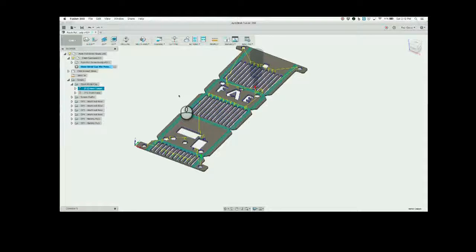And if Edwin needed these changes to the board, all he would need to do is open up the board file in Eagle and see that the Fusion Sync button is turned red. Whatever components he moved, of course we would make the modifications appropriately in Eagle as well, the traces and the components, because they need to be updated since you moved parts. As soon as you move a part, no matter what you do, you have to go edit those components back in Eagle. So we could go back into Eagle, rip it up, retrace, run the auto router, whatever tool you want to use, and then push it back to Fusion. That way they sync up. Yep.